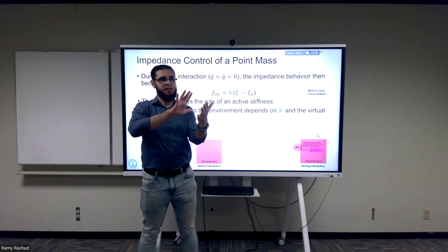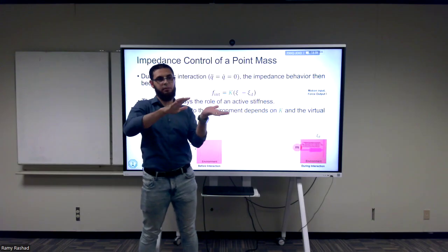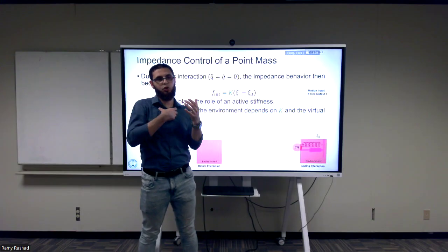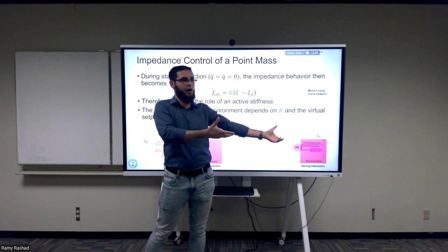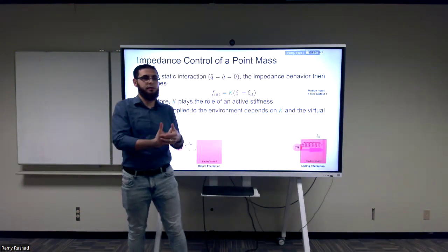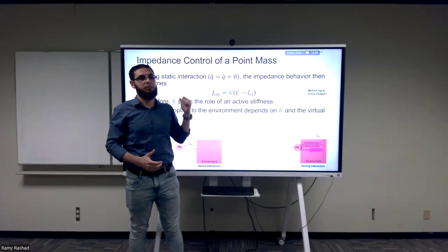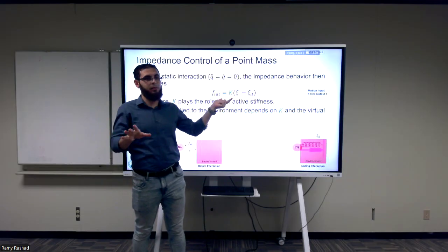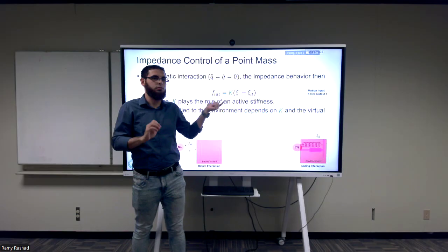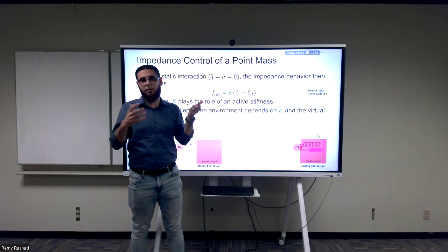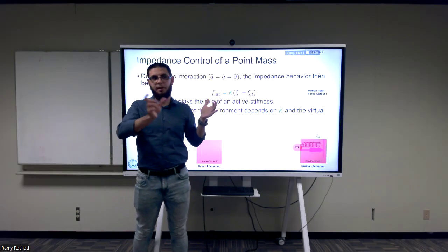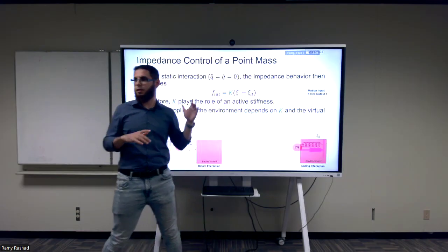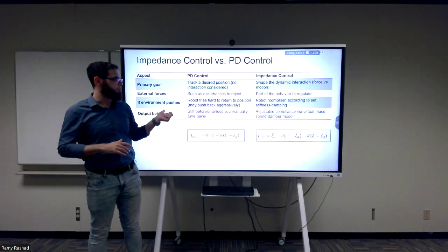And I'm also pushing with some stiffness. So I have the stiffness of the controller, and there's the physical stiffness of the environment. Both of them coupled together might make the system unstable. So when I'm choosing this, if I don't know anything about the environment, how can I control it? I must know something about the environment, and this is what we're going to be seeing. This something is called passivity. This will be the topic of next time, inshallah.